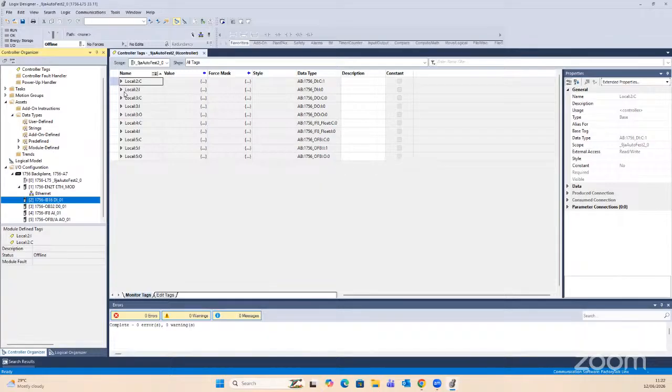In the early era of PLC programming, was it with Siemens or with brands like Allen-Bradley? From your IO addressing, you can tell the slot on which your PLC module was positioned. You can tell the slot, and you can tell the terminal it was terminated on.